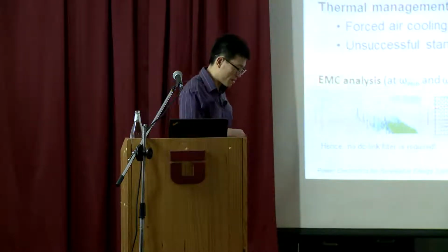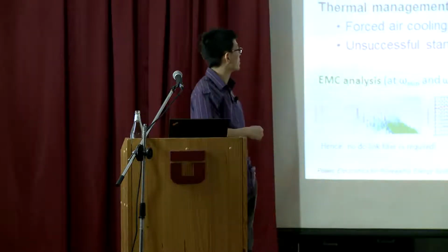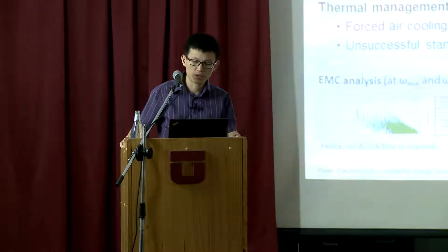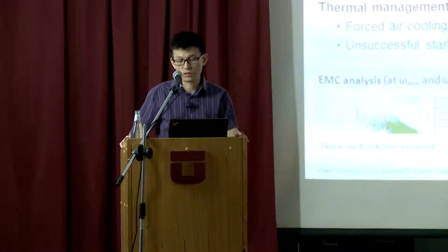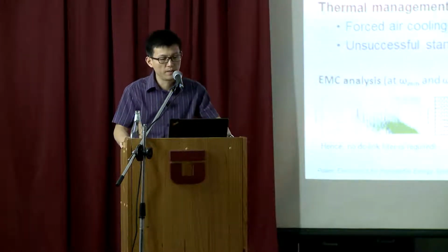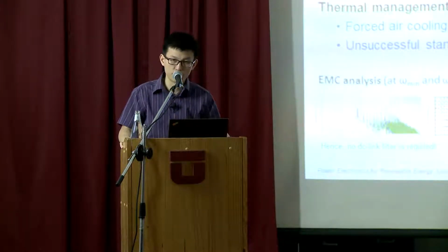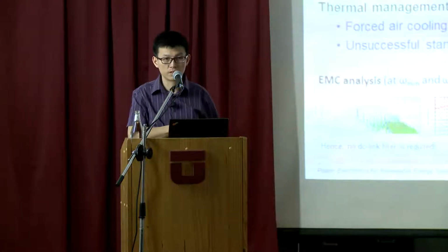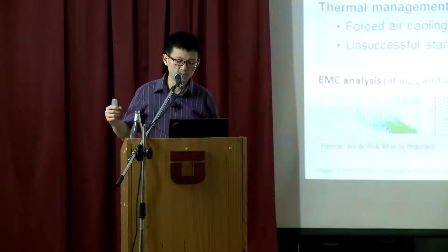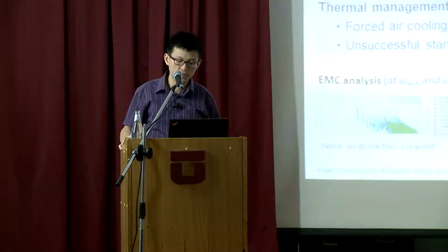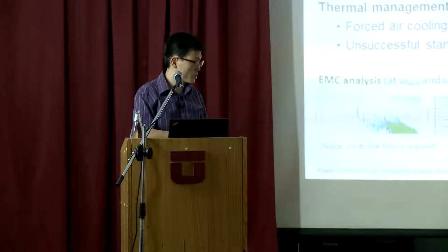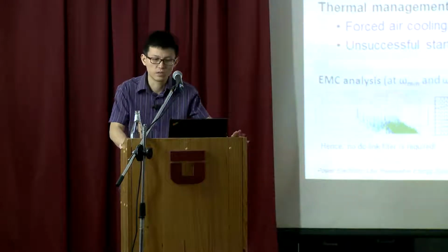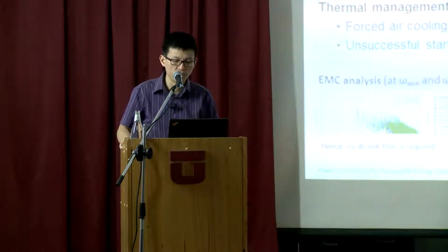So we used a 3-level converter at that time based on IGBT, of course, based on silicon devices, and mainly one consideration is the thermal consideration, because for a 2-level converter the losses in the converter are too high. For a 3-level converter, you can bring down the losses. One of the challenges for this converter is that it's in the parabolic space in the aircraft, so the ambient temperature we're looking at is 80 degrees, not like the 25 degrees we normally have in industry. But in aerospace, the starting point is 85 or 80 degrees.